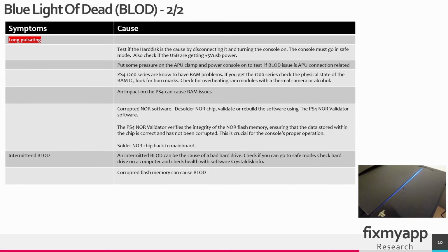A bad hard disk can also be a cause of a long pulsating blue light of death, and you can test it by removing or disconnecting the hard disk. Then the console must go in a safe mode. Also check if the USB is getting the 5V USB power.